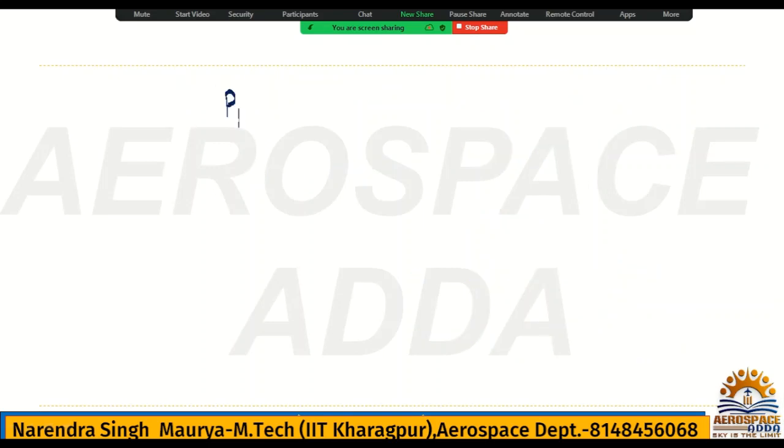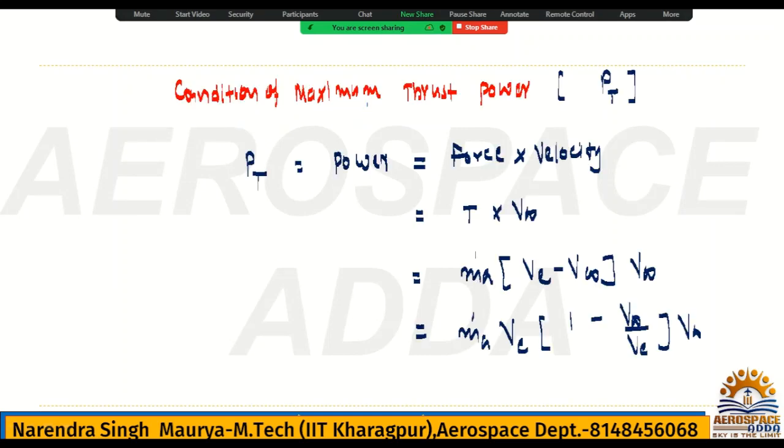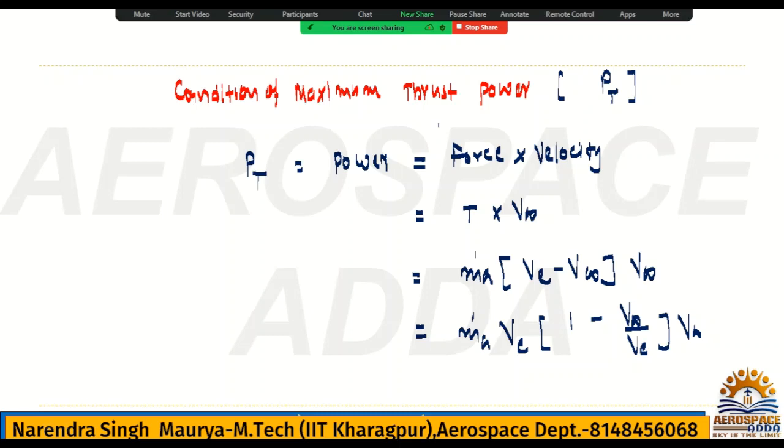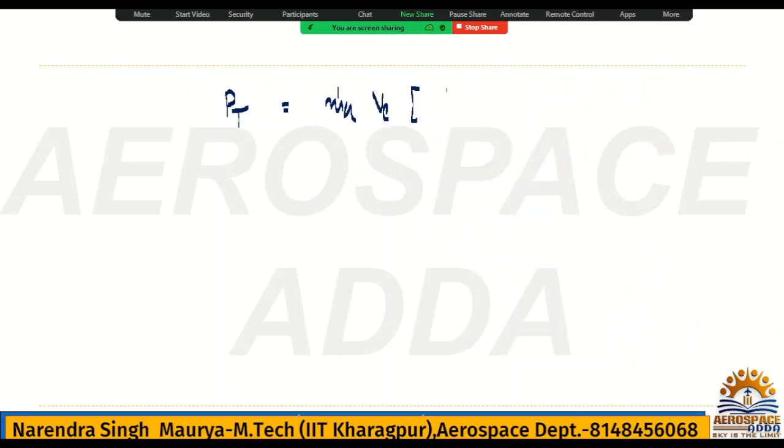So what will we have? PT, the thrust power, is equal to m dot a. If you take ve common here, you will have 1 minus v infinity by ve, and here you have v infinity.